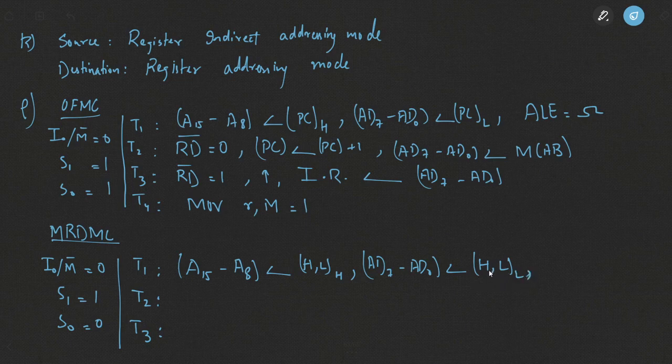Now in this particular instruction, the HL register pair is basically holding the address of the memory location. So we need to read that. Using these two, in the T1 state, the address bus will be loaded with the contents of the HL register pair. The most significant bits going to A8 to A15, the least significant bits going to AD7 to AD0, and address latch enable will be triggered. Fine. We have to do nothing with the program counter in this particular machine cycle. The program counter only keeps track of the instruction. So whenever the next opcode fetch machine cycle is triggered, it will read this PC.